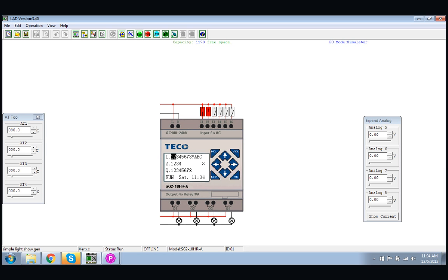So that's pretty cool. Another one is a water purifier, so that when a pressure sensor switch goes high and activates, it changes valve positions, activates a back flush cycle, stops the back flush cycle, reverses the valve position, and then gives light indicators along the way, as well as a text readout to show you what position it's in. So if this were, say, remote on a panel across the plant floor, you could look at the screen, if it's programmed to that level, and see the status or the condition of the current operation.